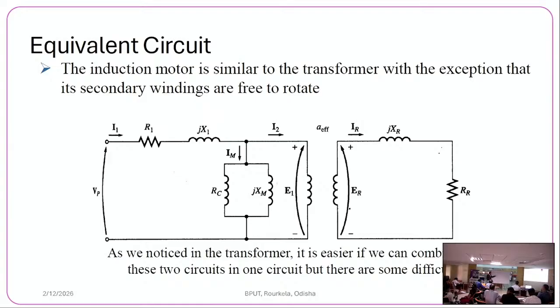But another line which I have drawn here is linking only with the stator. It is not linking with the rotor. If the flux is linking only with the stator but not with the rotor, it is leakage flux. It is not useful in power production. It is wastage. Similarly, this other flux, linking only with the rotor and not with the stator, is also wastage. This is rotor leakage. This is stator leakage flux, this is rotor leakage flux, and this is the useful flux, or mutual flux, or air gap flux.